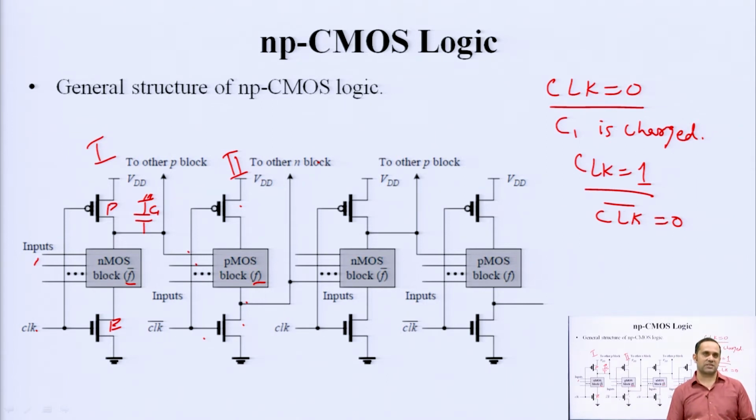One is in pre-charge, another is evaluating, when another is pre-charging, the next stage is evaluating and so on. So, this way they are not together charging or discharging, whatever is being transmitted from stage 1 is saved, it is isolated from next stage. So, the high output of stage number 1 does not affect whatever is happening at stage number 2, and here you take the output of stage 2, let us call it C2, capacitor C2, okay, and so on.